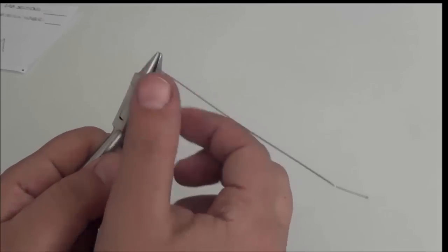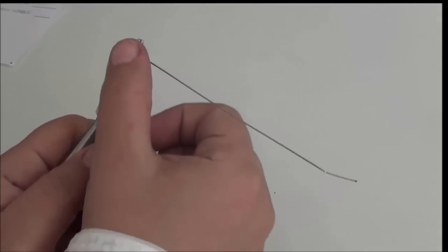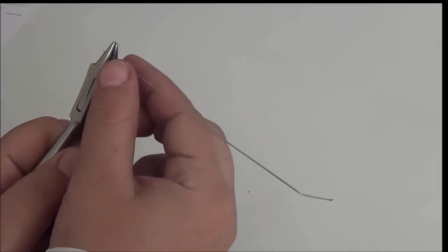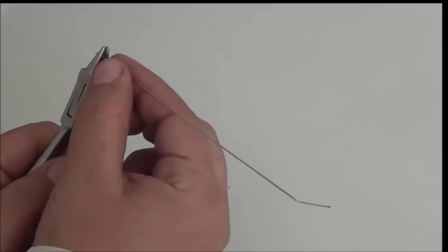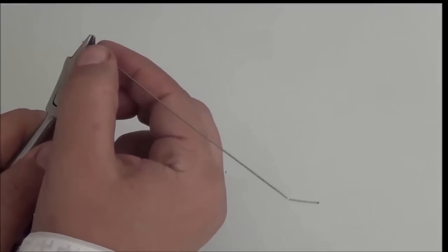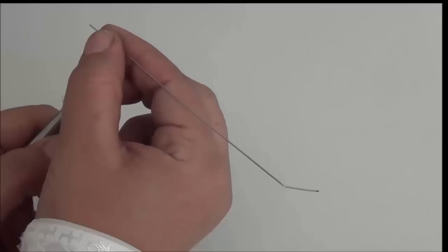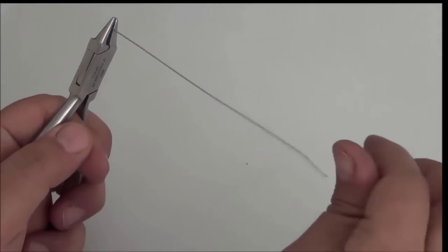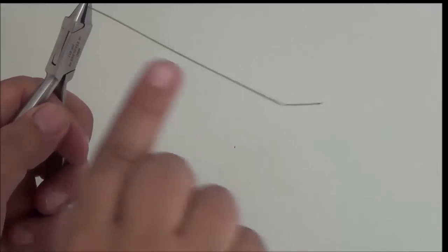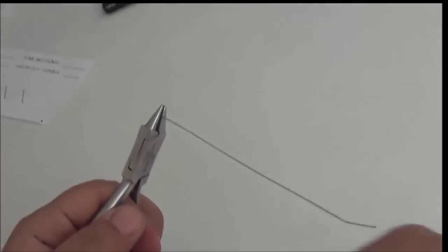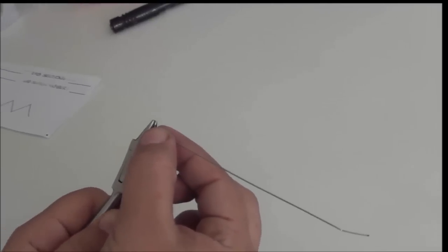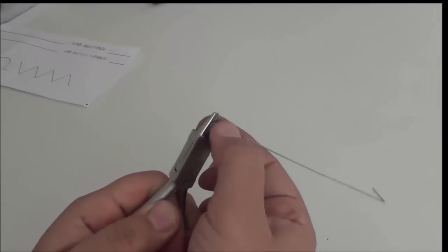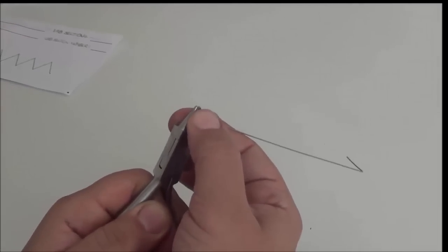And when I bend, I use my finger. So it's not the plier that's bending, it's my finger pressing against the plier. So when I want to bend, I press away from my body. So if I'm going to bend here, I'm going to bend in this direction. So I hold it. Make sure this is in the same direction I'm bending. It's not downwards, it's not upwards, it's in the same direction, perpendicular. Okay, and I begin holding it firmly and then begin bending. So it's firm pressure from my finger.